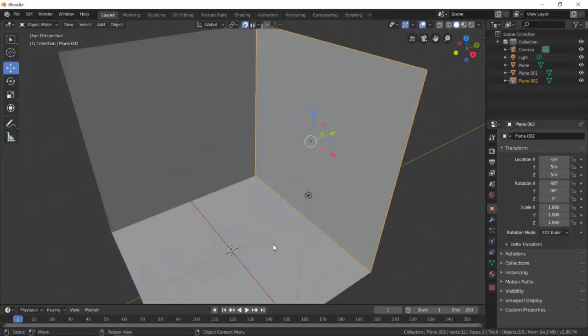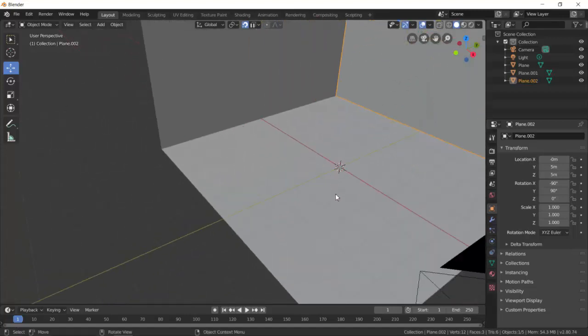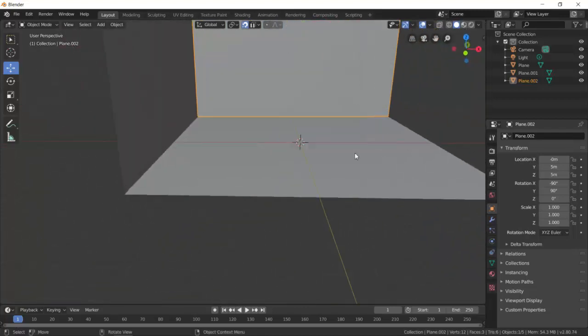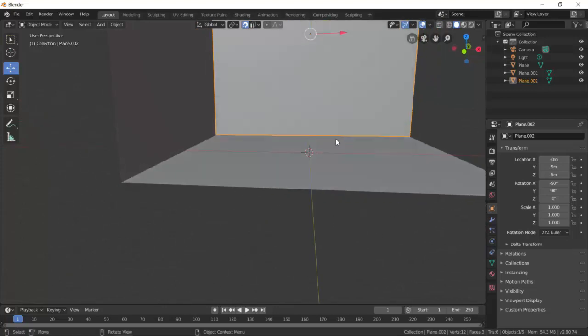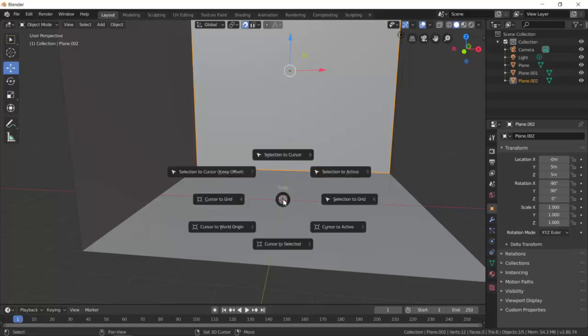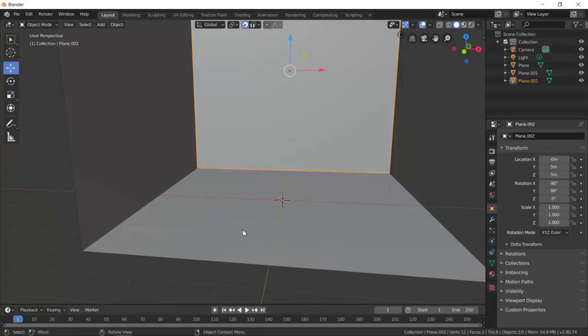Now today we're going to have a go at making like a cup and a saucer. So I'm going to start by picking the mesh shape that I think is closest to my cup. So that's going to be a cylinder. Now whenever I go Add Mesh, it always spawns to where this axis point is. That axis point I can move by going Shift S, and it brings up this. So move the active cursor to the world origin. So that's this point here. And I just let go of my mouse and it does that.